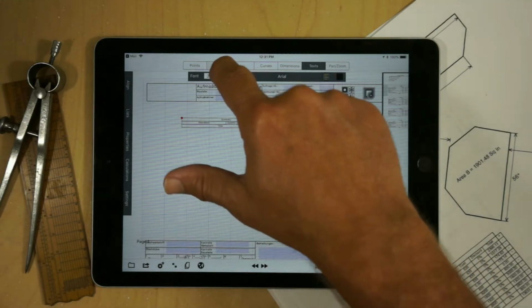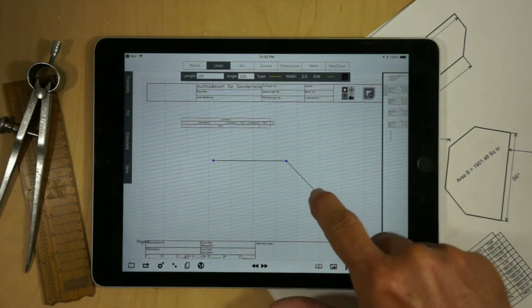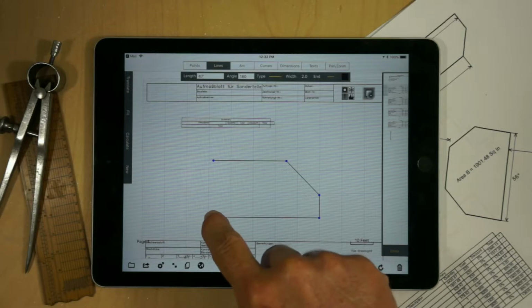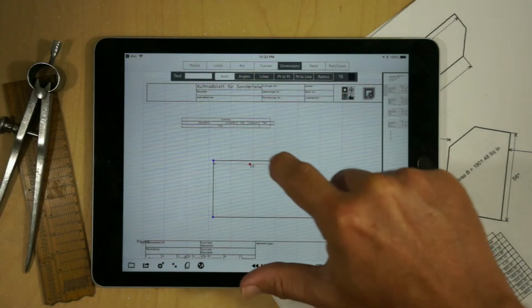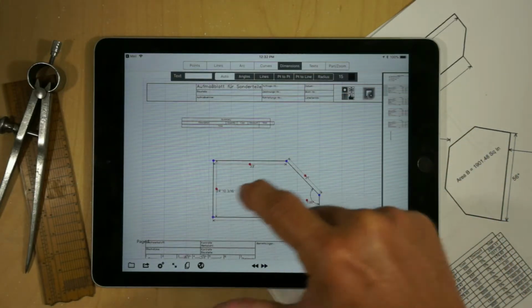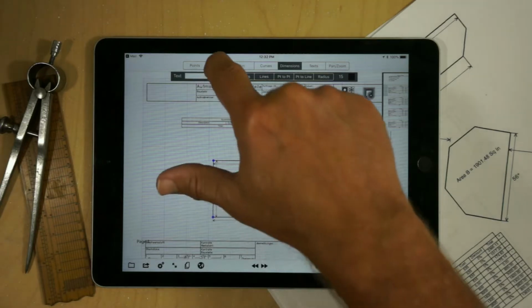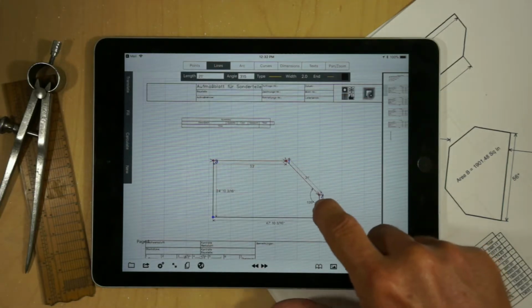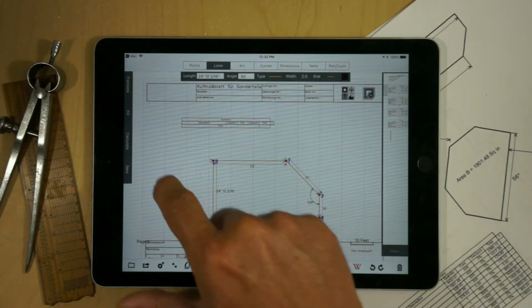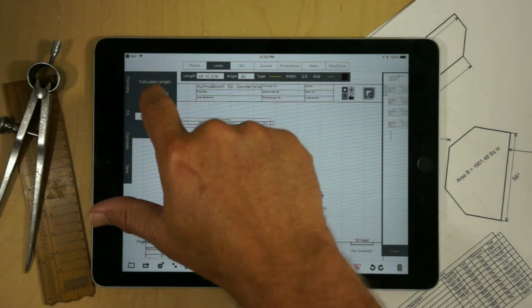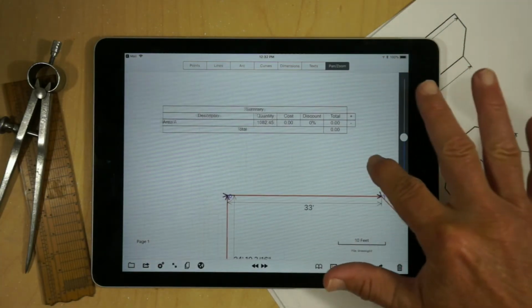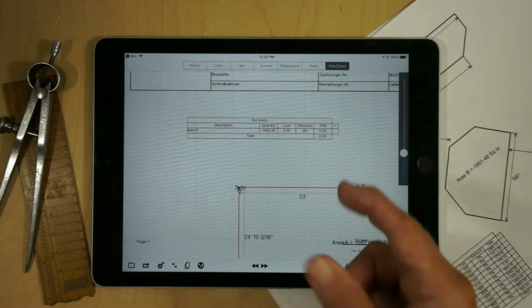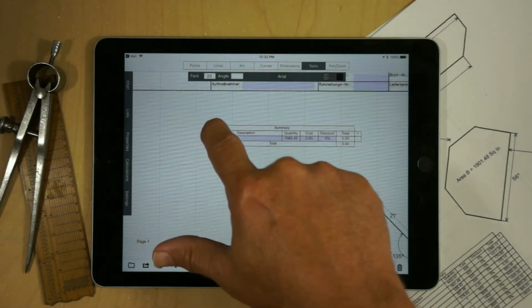And so, for example, if I calculated an area, and we can do something very arbitrary, there's my cross lines. We can drop in our dimensions, of course, but if we calculated an area and we would just select the lines around a closed perimeter and hit calculate area, we'll notice that that area has been calculated. And that's interesting, but that's as far as this particular type of table took it.